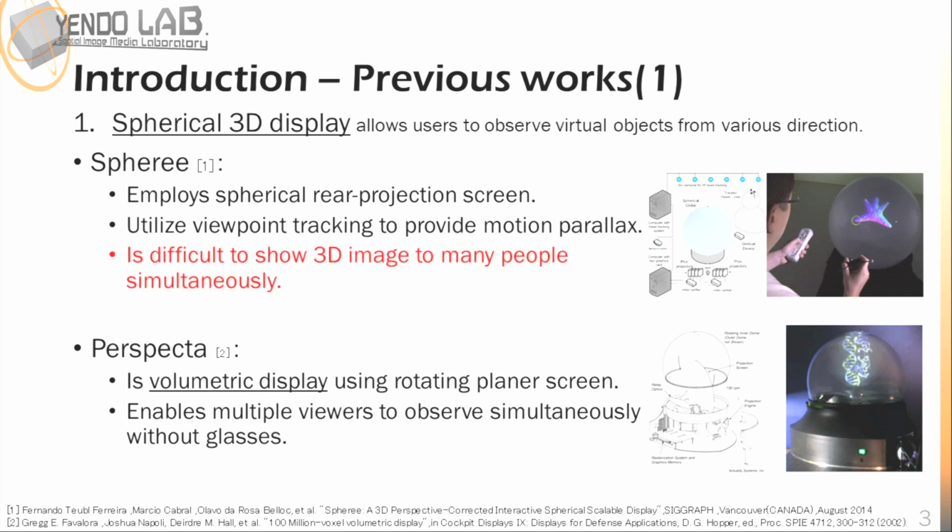On the other hand, this projector is a volumetric 3D display. This achieves floating light points in a spherical volume by rapidly rotating a circular screen. The screen displays a sectional view of the displayed object. Thus, this display is capable of displaying 3D objects for multiple viewers without glasses. However, volumetric displays are not capable of providing complicated optical effects like the occlusion effect or refraction.